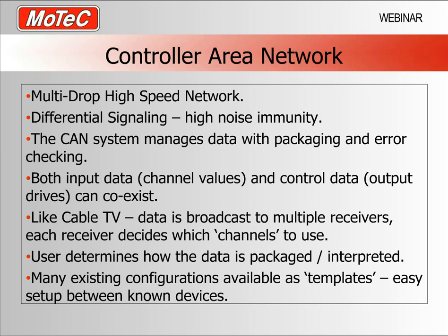Now, CAN, due to all of these elements of flexibility, can be extremely complicated, and there are also a lot of conventions used by manufacturers and indeed by MoTec, which allow people to select defined CAN addressing and data, which we call templates. When you're using a MoTec device, it's quite simple, in fact, to set up communication between multiple devices, because each of those devices has a library of templates that allow you to just select what you wish to send, and then the other devices will have a similar template that allows you to bring that data in without even necessarily understanding how the formatting works.